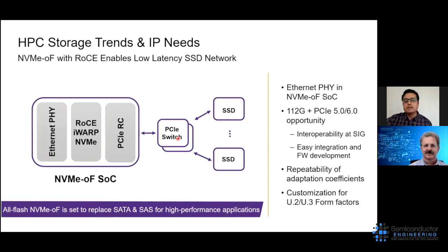So they have to do interoperability, and they have to do multiple power up and power off cycles. So they're asking us for repeatability of adaptation coefficients. Meaning if the SerDes is turned on and off, let's say thousands of times, how does the SerDes behave? Does its adaptation coefficient, does its performance change? That's a crucial parameter for them. So this is asking us very new questions which were never asked. So there are some changes or some optimization in 112 gig SerDes which is needed for this.